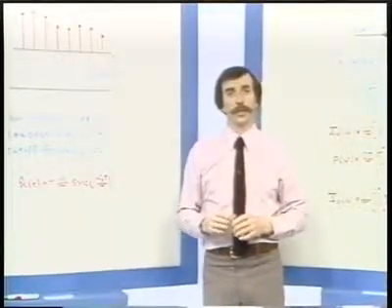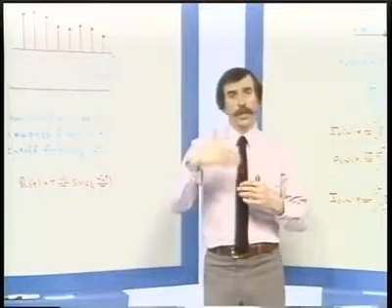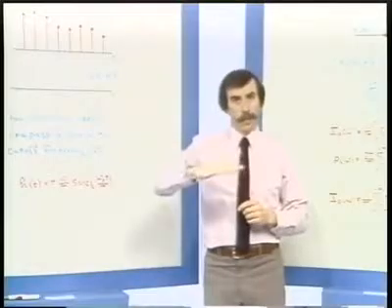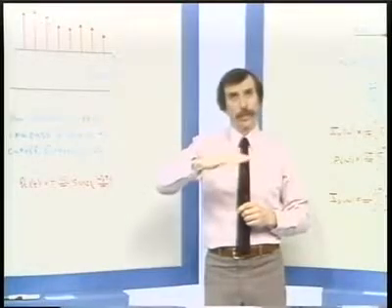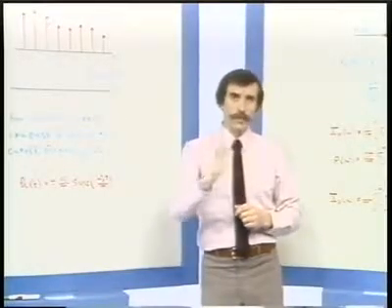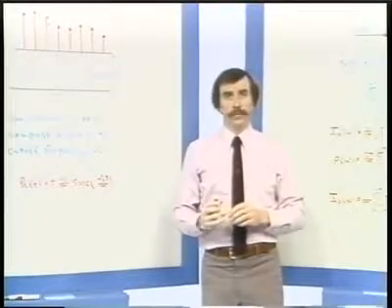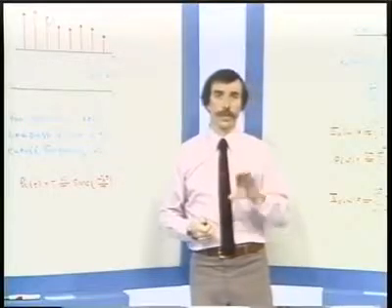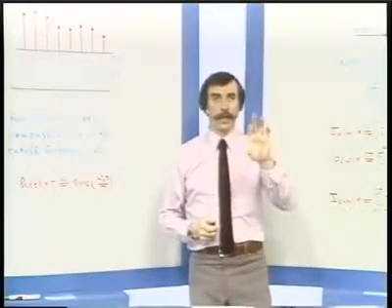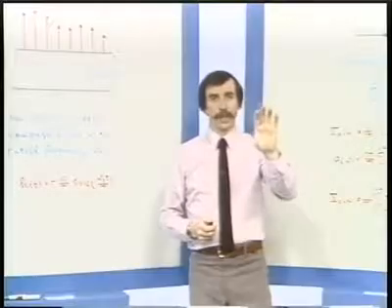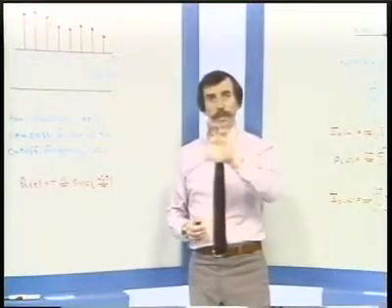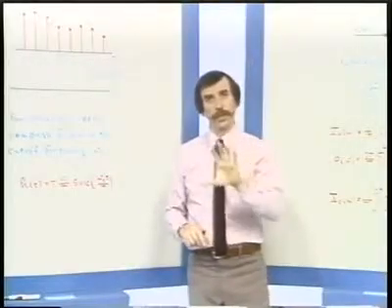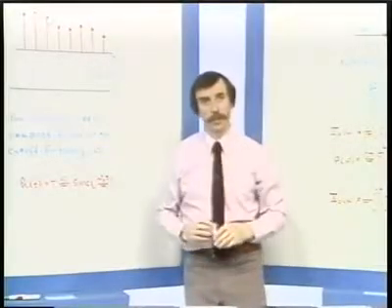And what you'll see in the computer movie is essentially an original waveform, which is a continuous curve. And then below that in the movie is a train of samples. And then below that will be the reconstructed signal. And the reconstruction will be carried out by showing the location of the impulse response as it moves along in the waveform. And then the reconstructed curve is simply the summation of those as that impulse response moves along.